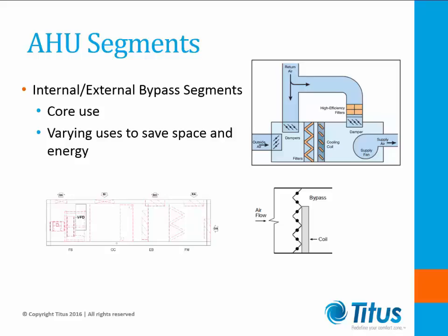With regards to controlling the units, the cooling coils are controlled by space humidity, while their variable air volume fan is controlled by floor pressure. And the bypass section will now control supply air temperatures.